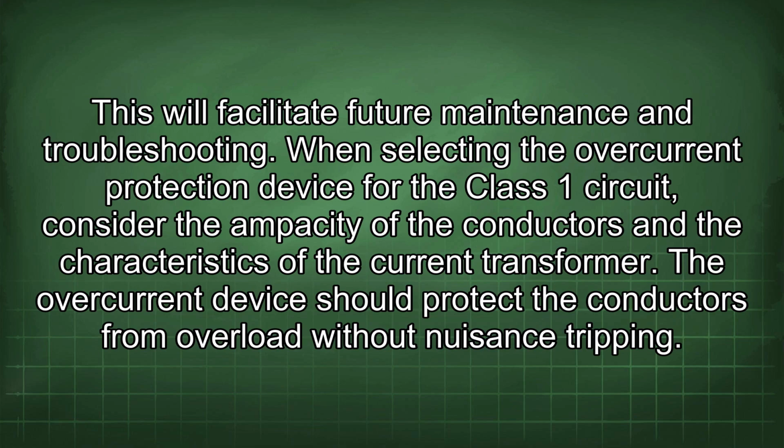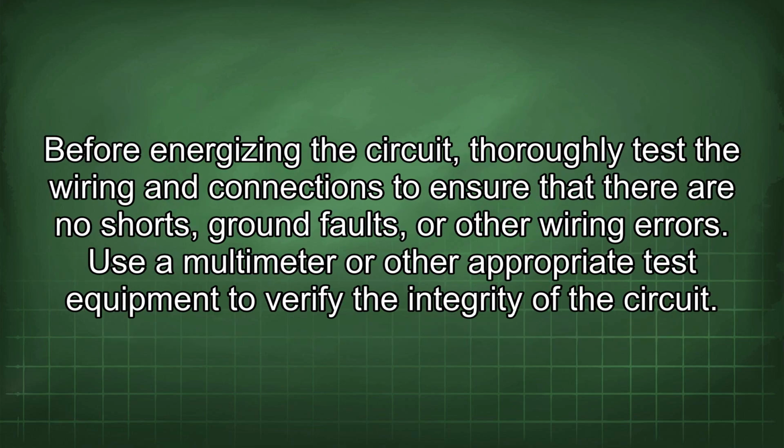The overcurrent device should protect the conductors from overload without nuisance tripping. Before energizing the circuit, thoroughly test the wiring and connections to ensure that there are no shorts, ground faults, or other wiring errors. Use a multimeter or other appropriate test equipment to verify the integrity of the circuit.